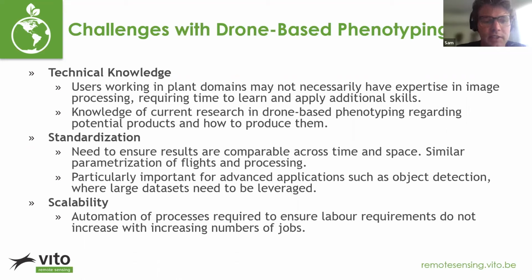In addition to this, there can be difficulties in standardizing your products. So if you are performing flights, let's say on an ad hoc basis, you might end up collecting them with different settings. So you might have, in the end, very different resolutions of the flights. They might be collected under dramatically different lighting conditions, which makes it harder to compare your results and more prone to different errors outside of the actual difference within the field.